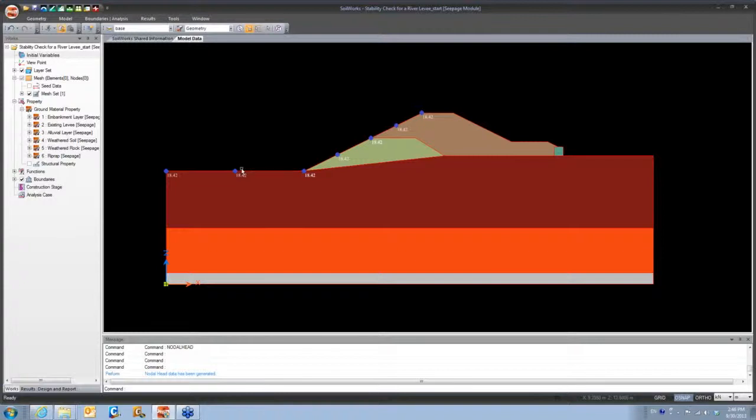Okay. So it says 18.42, which just means the water level is 18.42 meters, with respect to the origin. The bottom left corner here, where my axis is, is 0, 0. So 18.42 meters is near the top of the levee, but not completely, to the critical point. You see the axis at the bottom left, that orange or yellow square? That's the origin, 0, 0. And all of these nodes here say 18.42. That's referencing the height of the water.